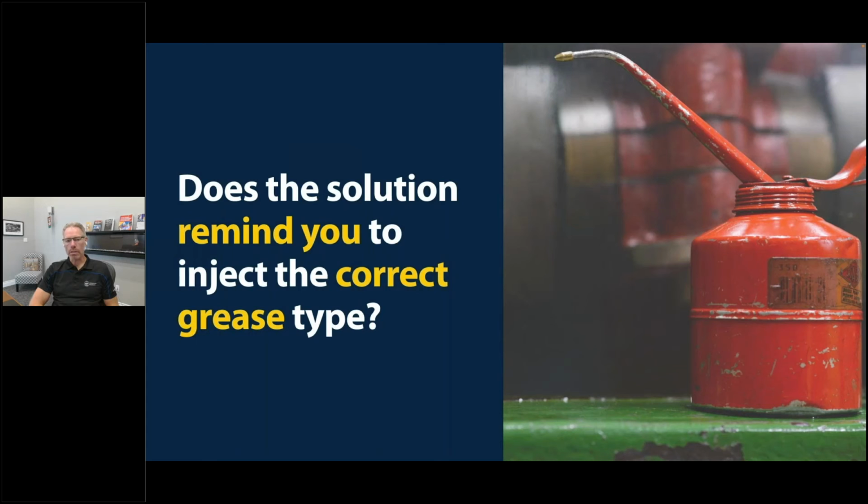Does the solution that you're going to use for acoustic lubrication remind you to inject the right grease type? We all know what happens if we mix incompatible greases. I have a fairly long story about a summer intern who was told to grease water pumps in a wastewater treatment facility in Southwest Florida. He was given graphite grease to grease just the grid couplings. Well, he thought he'd go above and beyond, and he decided that while he's there, he might as well lubricate the pump and the motor as well. Needless to say, they had a big job ahead of them to undo that damage.